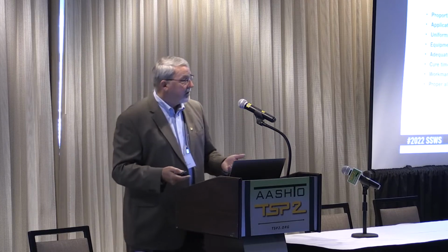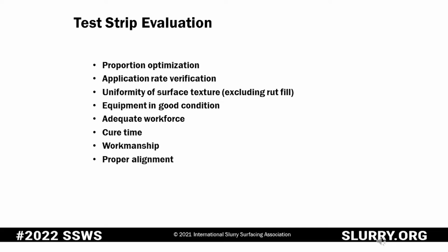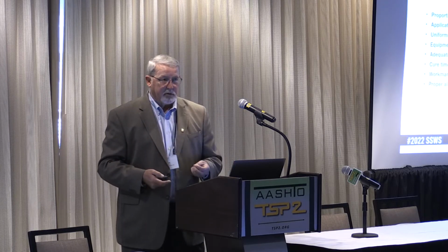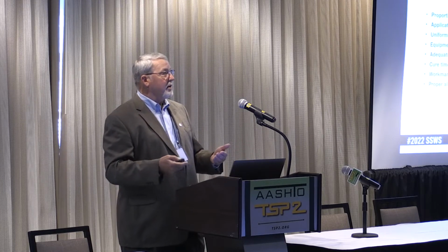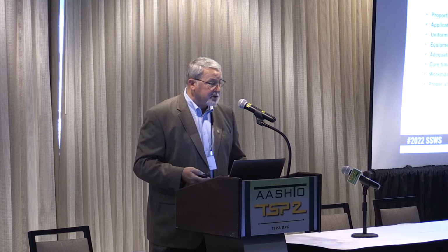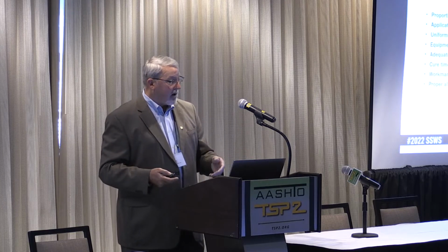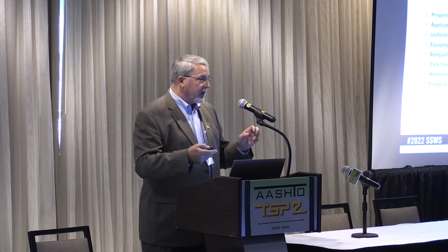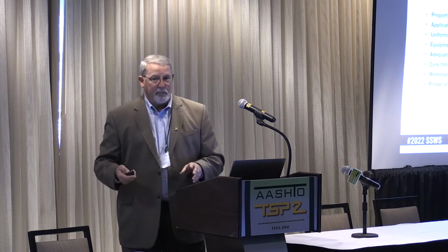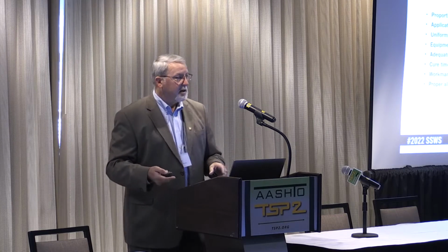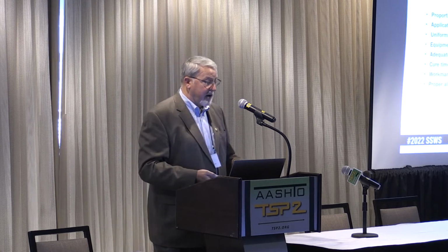Adequate workforce. Do they have the workforce on hand during that test strip and for the rest of that project that they're going to need to apply those materials adequately? Cure time. Cure time is a big issue. We want good return to traffic timing, and it's probably a bigger issue to the contractor than it is to the agency, so it's very important. But keep in mind that cure time is not directly related to overall long-term performance. Just because it cures fast does not mean that you're guaranteed long-term performance. It just means it's setting up quick and you're going to have good return to traffic.